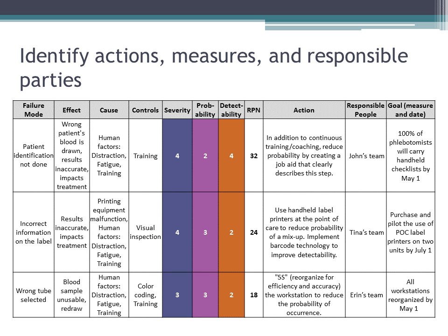So our actions are now listed in the table. These are the improvements that we want to make in order to reduce the risk associated with each of the riskiest failure modes. Notice we've got the 3 riskiest failure modes as determined in our hazard analysis listed in this table. And at this stage, we also need to identify who will be accountable for implementing the actions and what the goals and time frames are.